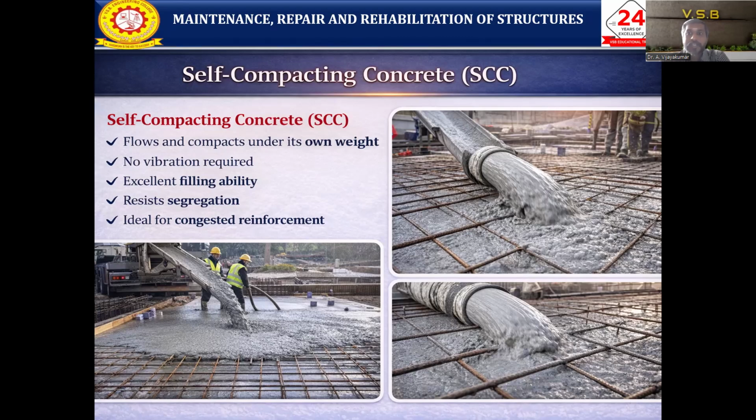It resists segregation, but in normal concrete segregation and bleeding will be there. But here we are totally avoiding segregation. Okay, so it is ideal for congested reinforcement. In normal, conventional concrete, with congested reinforcement we cannot achieve proper compaction. But the main advantage of self-compacting concrete is that even with congested reinforcement we can pour concrete